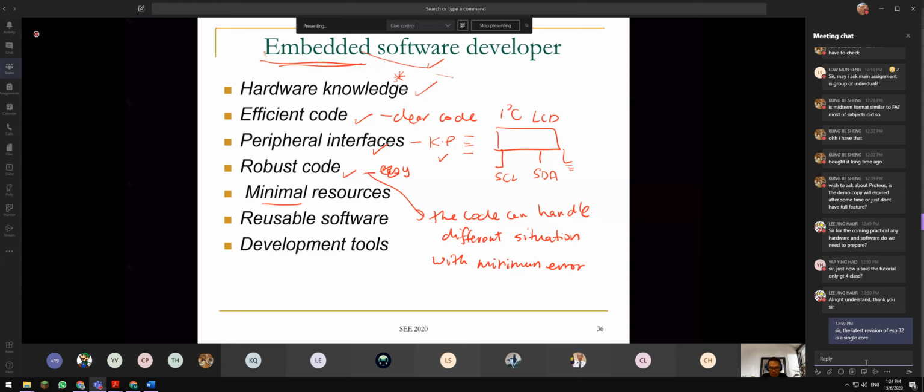In debugging, you can use an oscilloscope, or use something like the PICkit 4 to put a breakpoint and do real-time debugging. When you involve the PICkit 4, it costs money, so you're already utilizing some hardware debugging tools. Things get more expensive if you're using BDM, like the in-circuit debugging just now. All these things cost money. So if you're able to solve your problem with minimum resources, that's fantastic. Remember, debugging is the toughest part of embedded system design.